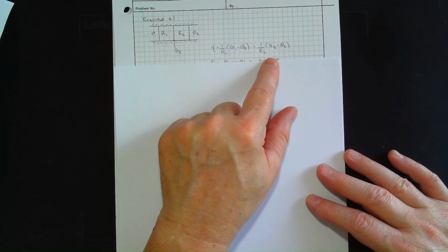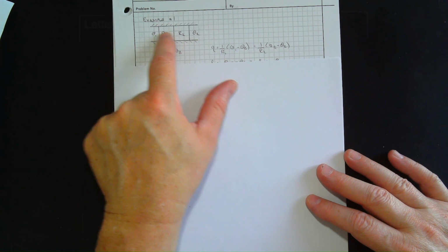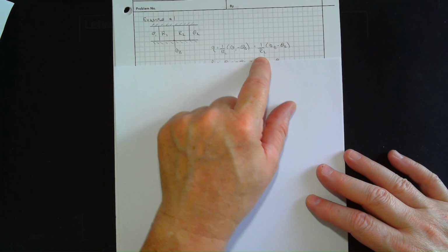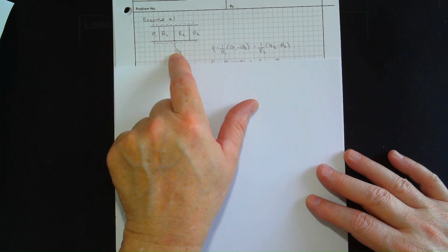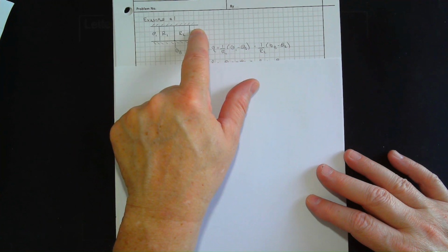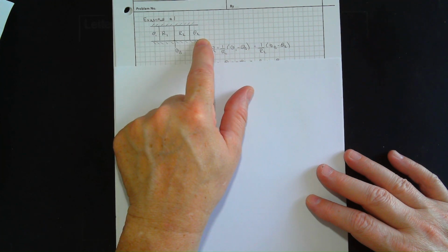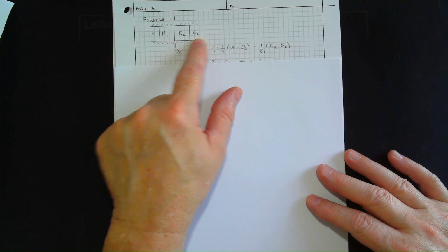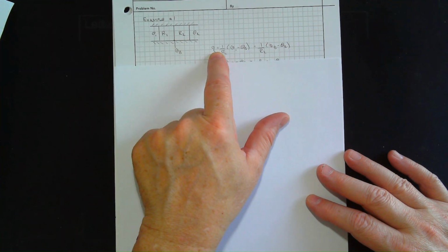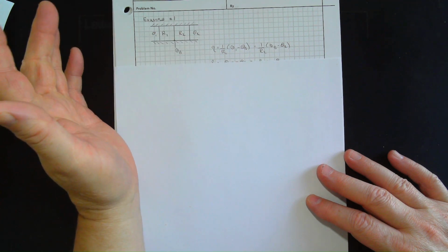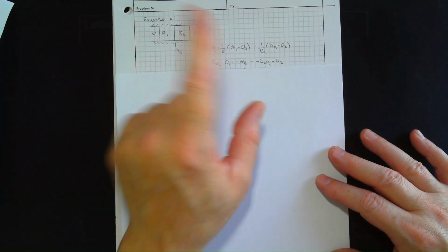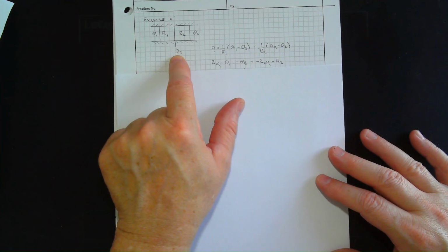Likewise, for R2, the heat flow, whatever goes through here, can't be stored, so it's got to keep on going. So we'd have 1 on R2 times theta B minus theta 2, all assuming the heat's flowing this way. Again, if this is hotter than this, it'll go the other way and this will wind up being negative. You'll know your assumed direction was wrong. Nothing wrong with that. All right. This theta B we really don't care about.